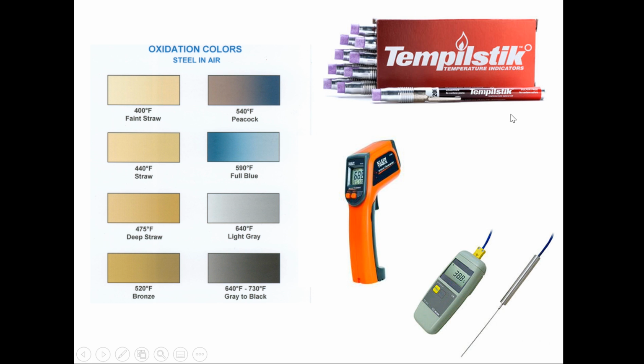Every good tool steel welder has 2 temp sticks with them. One that represents the highest temperature they have, and one that represents the lowest temperature that they are going to achieve. The highest temperature represents interpass temperature. The lowest represents minimum preheat. Now, temperatures can be assessed with infrared. I didn't bring my FLIR, but I will be doing a demonstration. I'll bring my FLIR camera for any type of practical training that's done, and we can do a little bit of a survey of your components.